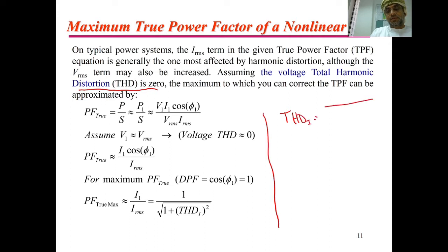Well, as you know, it will be the square root of the harmonic currents. If I consider only the odd harmonics now, so I3 squared plus I5 squared plus I7 squared plus and so on, let me take this H, since H will be those numbers, divided by the fundamental current, the root mean square of the fundamental current, right?